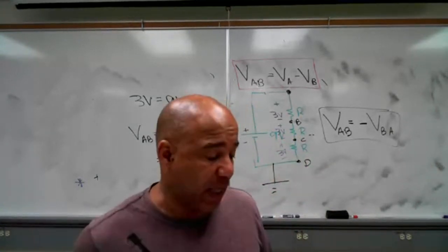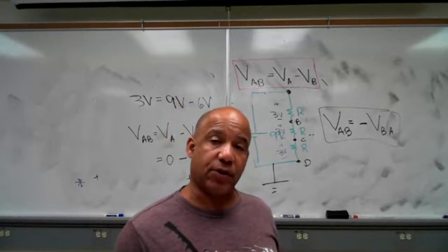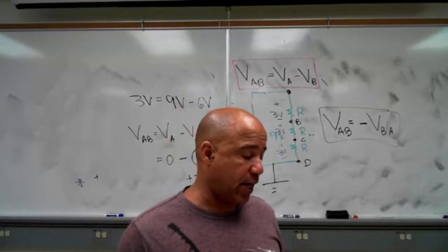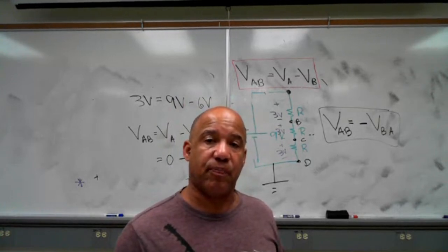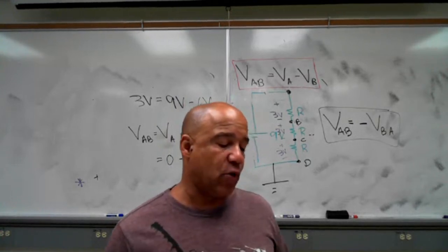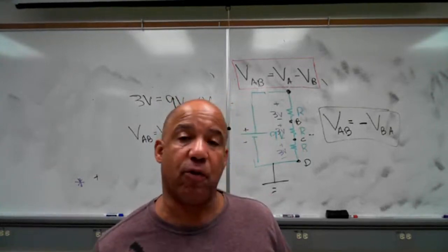So what you're going to do first is fill out table 4.1. You're going to get your meter, find those 3 resistors. The color-coded values are listed in table 4-1. Measure them to see what your measured values are. Once you do that, you're going to build the circuit in figure 4.2.